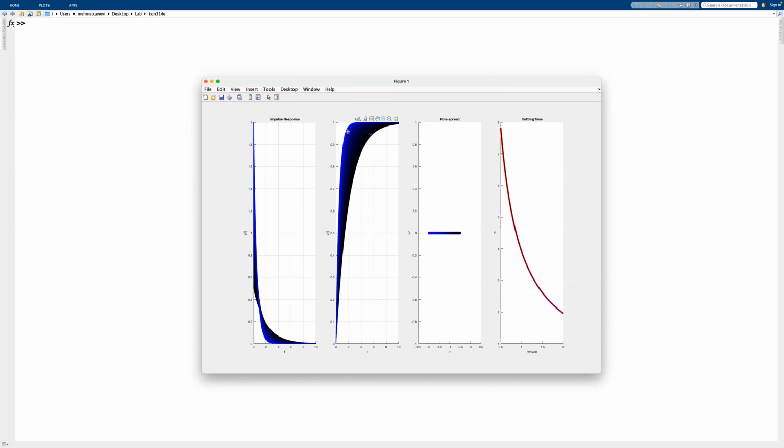And of course, the step response is also always increasing, and it'll just settle down. It will just stop here. It never decreases because we don't have overshoot. If we would have had some overshoot, we would pass this line, and at this point we need to decrease to come back to our value which we are going to settle down. So that's the reason why we have no negative part in our impulse response, which is also quite important to notice.